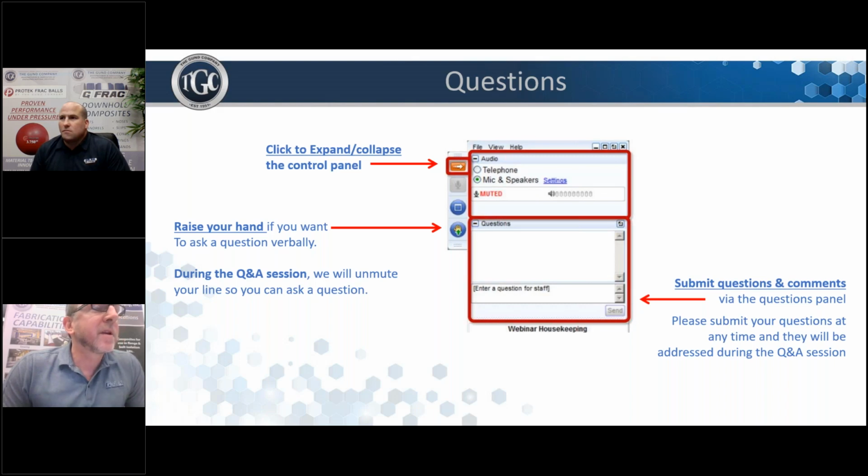This sounds like maybe a good question for a compounding or an injection molding situation. You want me to try to tackle that one? Sure. I was just going to add that random fiber orientation would have a lot to do with it, and also the distribution of the resin.